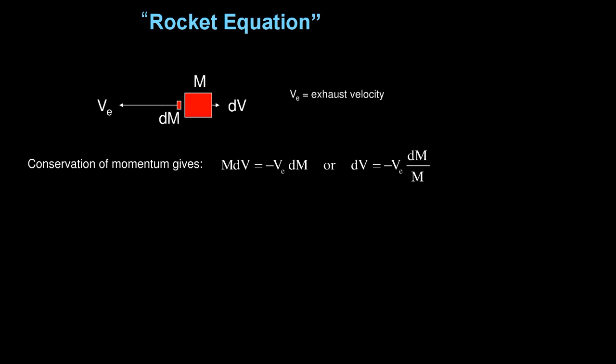And when you do that, you run into 2 problems. The first one is that by adding propellant, you make the missile heavier, so that the thrust has to lift a heavier missile and is therefore less able to accelerate it. And the second problem is a somewhat surprising result from physics, which is the rocket equation. And here's the way to think about this. Thrust needs to do 3 things. It needs to accelerate the mass of the missile, even in the absence of gravity. It needs to lift the mass against gravity, and it needs to make up for atmospheric drag.